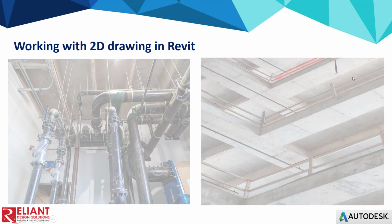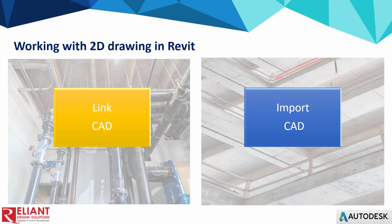This slide, I will talk about ways of working with or bringing in your 2D drawing file inside Revit. There are link CAD file and also import CAD file. Link CAD file is similar to Xref in AutoCAD. It just becomes a reference file.